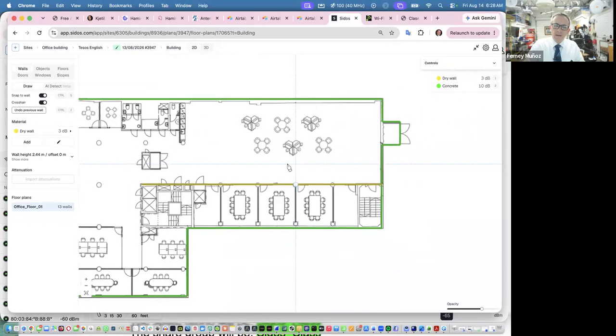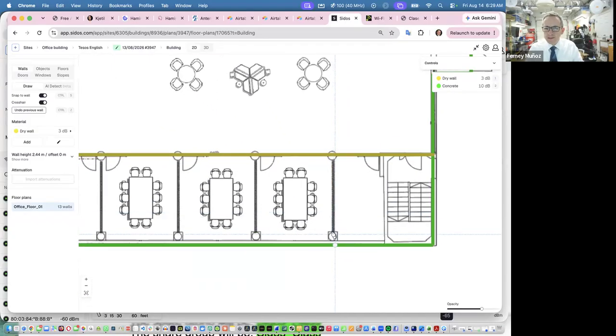Let me drag, I'm using the wrong button. Hang on. Then notice that as I move the mouse, if I, for instance, want to draw this wall and that wall and this wall, as soon as I get the mouse nearby, see this white dot? That snaps to there. Even if I click here and there, it snapped to the one on top.